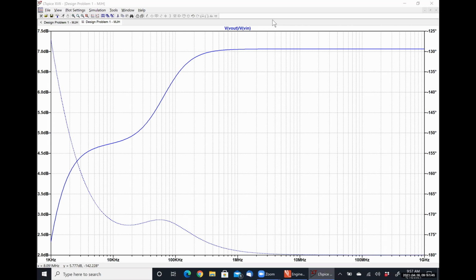So when we are dealing with the circuits in both the low frequency band and the high frequency band, it's perfectly reasonable for us to use our DC approximation for our transfer function between those two node points here. We're skirting around that because we're dealing with resistor only circuits right now. But once we get into circuits where we're including all the capacitors, those DC gain relationships that we developed are exactly the relationship between node X and the output node. So we don't have to rederive all that again.